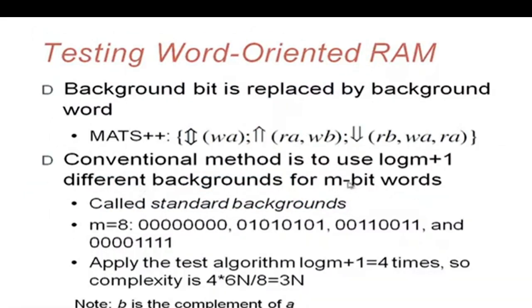Testing word-oriented memory. So till now, we considered a bit and the background was a bit. Now when we are going for testing the word-oriented RAM, the background bit is replaced by a background word. So in MATS plus plus, we are writing the background word.